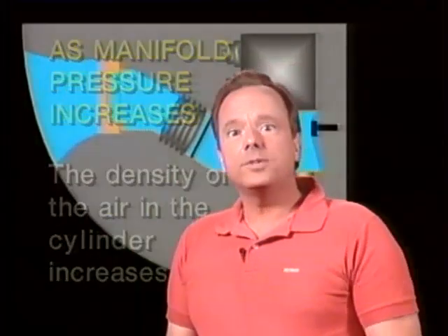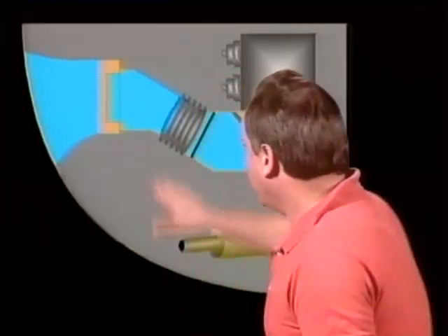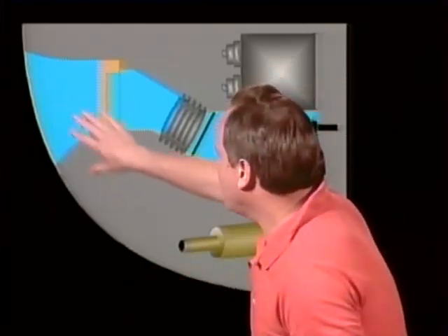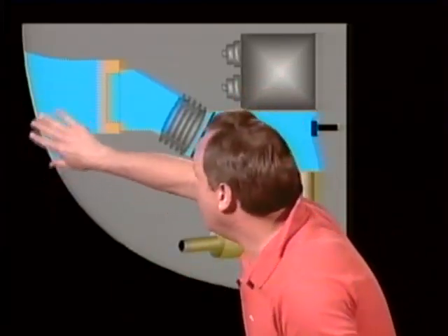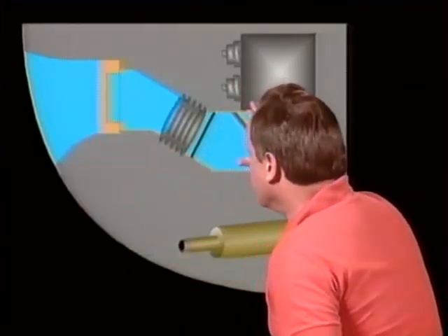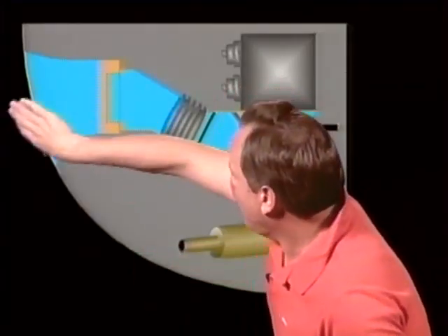They're also going to ask you, what's the action of the scoop at the very front of the engine here? They call it the air scoop, carburetor air scoop. Well, it's a real easy answer. The purpose of a carburetor air scoop is to supply air to the carburetor. But it may also increase the pressure of the incoming air by ram effect. In other words, on some airplanes, as the airplane goes through the air, it rams the air in the front of the intake system and increases the manifold pressure very, very cheaply and efficiently, kind of a poor man's turbocharging. So the carburetor air scoop can supply air to the carburetor and provide ram effect.